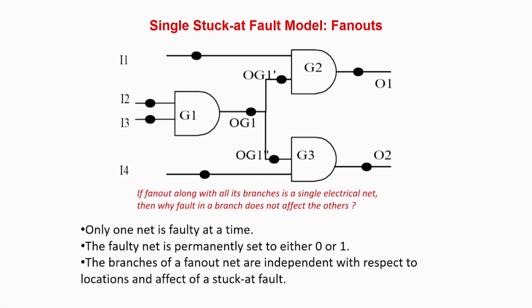defects. Some people have modified the fault model for fan out, but I am just showing you the stuck-at fault model. For a circuit like this, you have to point out all the nets of the circuit, and verify that none of these lines have a stuck-at 0 or stuck-at 1 fault. For example, first we assume there is a stuck-at 1 fault here, apply certain inputs and see that the stuck-at fault is not there. Then you erase it and take a stuck-at 0 fault, apply an input pattern and see that the stuck-at 0 fault is not there. You reiterate for all the lines of the circuit and then your testing is done.